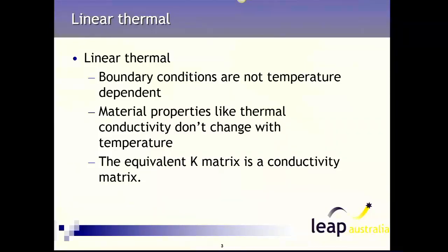With a structural simulation, we have this concept of a stiffness matrix, which is mostly based off displacements. In a thermal model, this K matrix is called the conductivity matrix, because we're basically solving a conductivity problem in a thermal simulation.